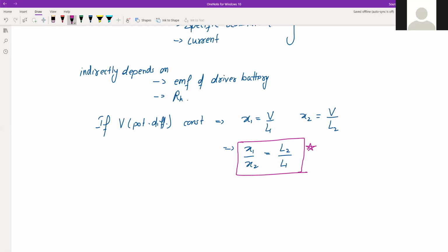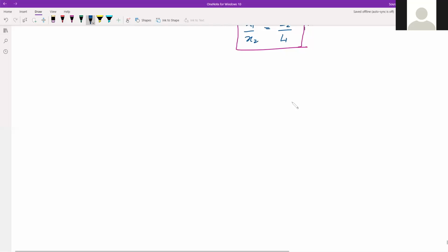Now if two different wires are connected in series to a potentiometer wire, then again the potential difference will change. And if the length of the potentiometer wire and the potential difference across its ends are kept constant, and its diameter is changed, then the potential gradient remains unchanged, and the value of x does not change with any change in the secondary circuit. These are the points which we have to note and take care of.